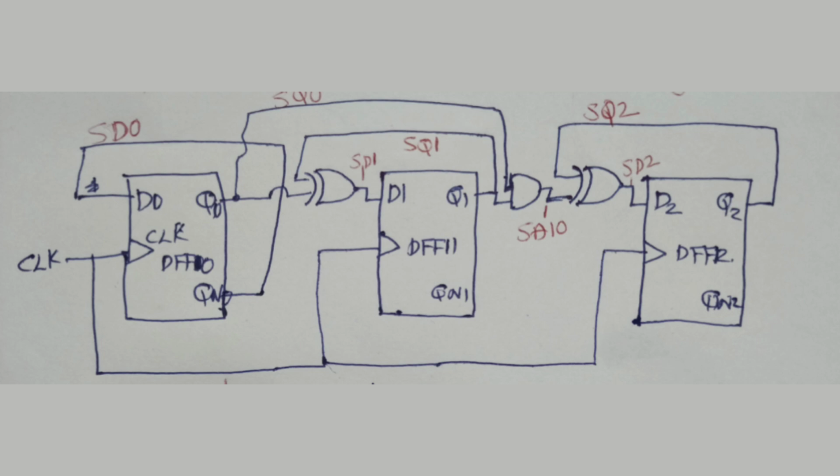Before directly discussing the Verilog code, let's have some preamble for this circuit. This is a 3-bit synchronous up counter. That is, it starts its counting sequence from 000 to 111. So with 3 bits, we will have 2 raised to 3 equal to 8 states in the sequence.